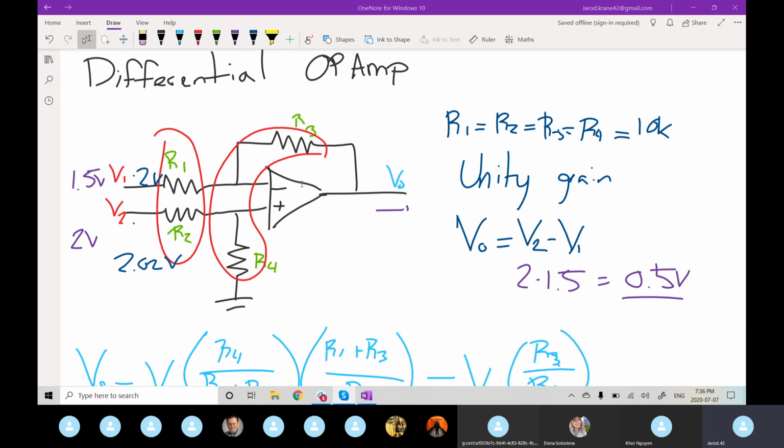And a proper boost or buck converter is much more efficient. This is more for instantaneous signal level amplification, better for reading signals, basically taking small signals and making them usable or readable, instead of using it as a power system.